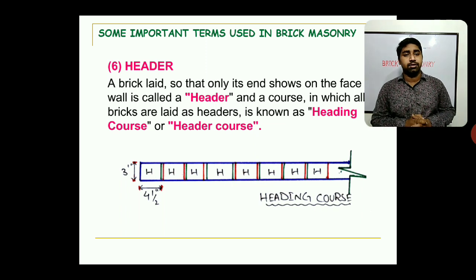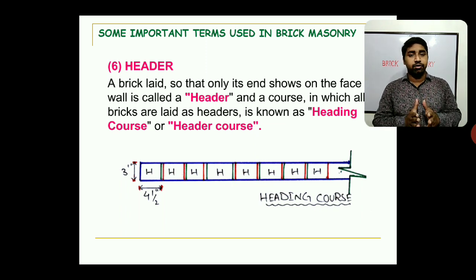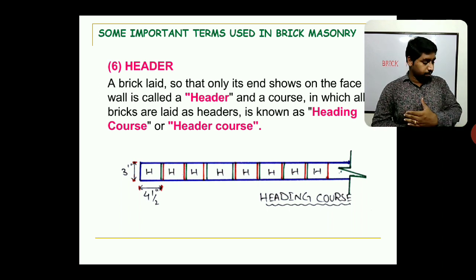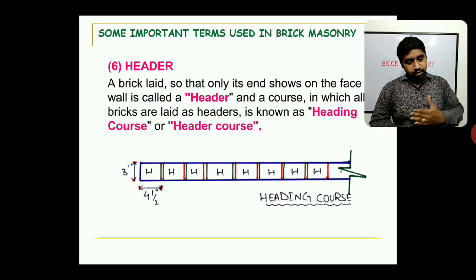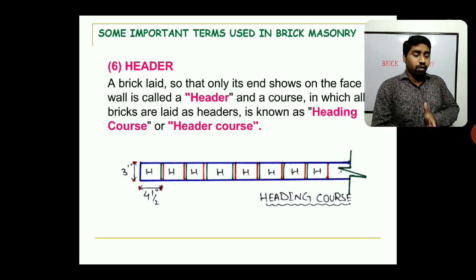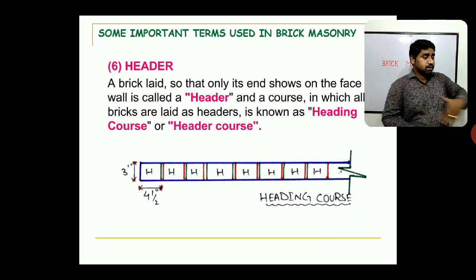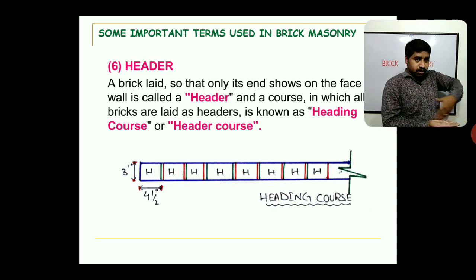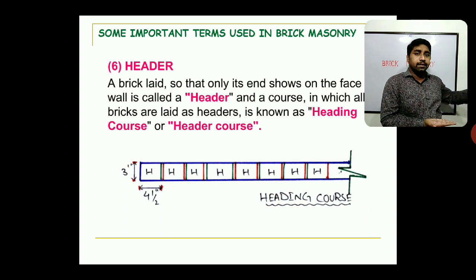What is this header course? First of all we have to know what a header means. Instead of laying the bricks along the face, if you lay the bricks perpendicular to the face of the wall, then it is called a header.